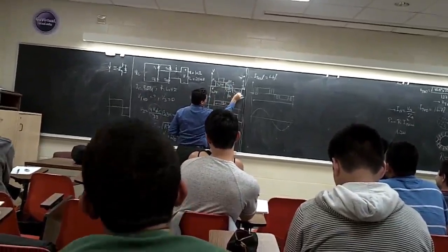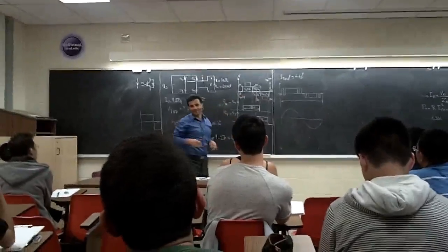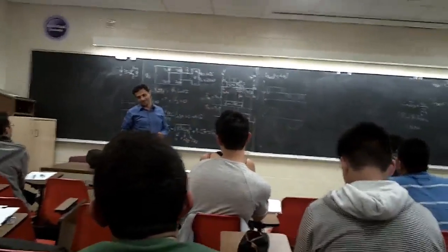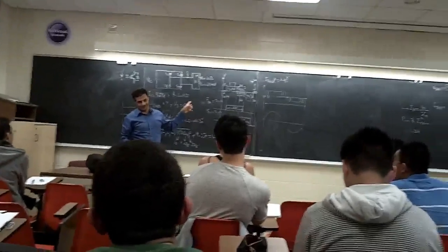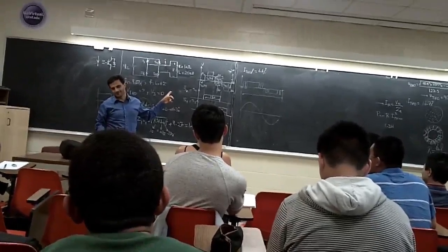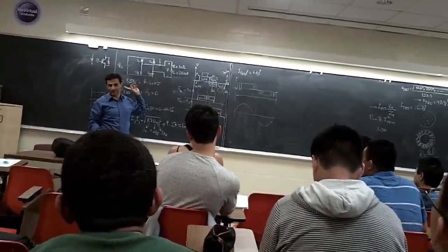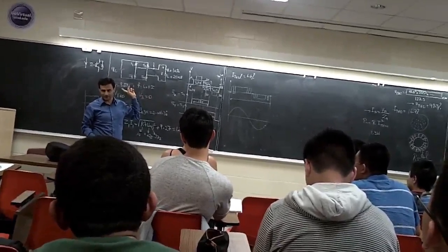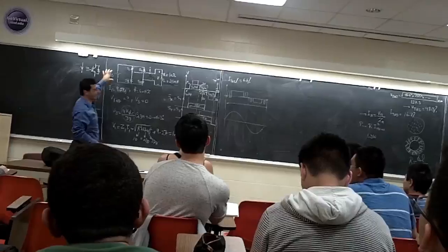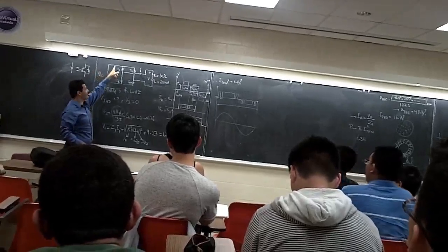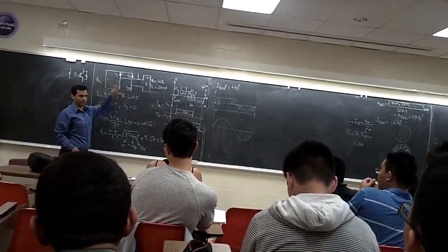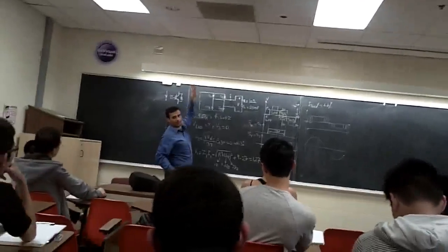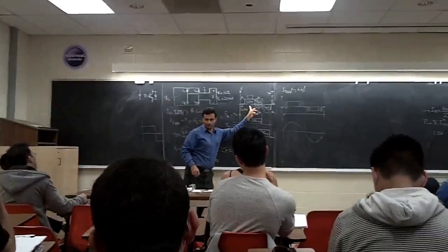But how are you going to do that? Use 2 DC buses and more switches to control it. Yes, they call it a multi-level inverter. You can do this one. That's what I meant when I said we have neutral point balancing and those kinds of things. See here, I have only one VDC. But if I have a neutral point here, right now I have only one parameter, VDC. There I can go up, down, or in this case 0, right?